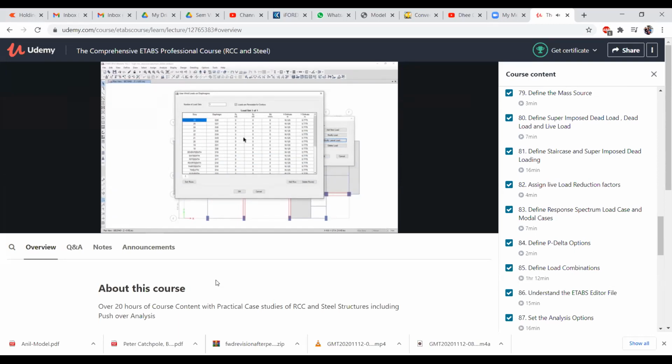Now what kind of load shall we apply? We can apply point load and moment on the diaphragm center. And what is the ordinate of that diaphragm center? This is the ordinate of that diaphragm center. As our building is symmetrical, this value is the same for all the floors. Otherwise, if our building is unsymmetrical, this value is different for all the floors. So what we need to do here is just enter the point load here.